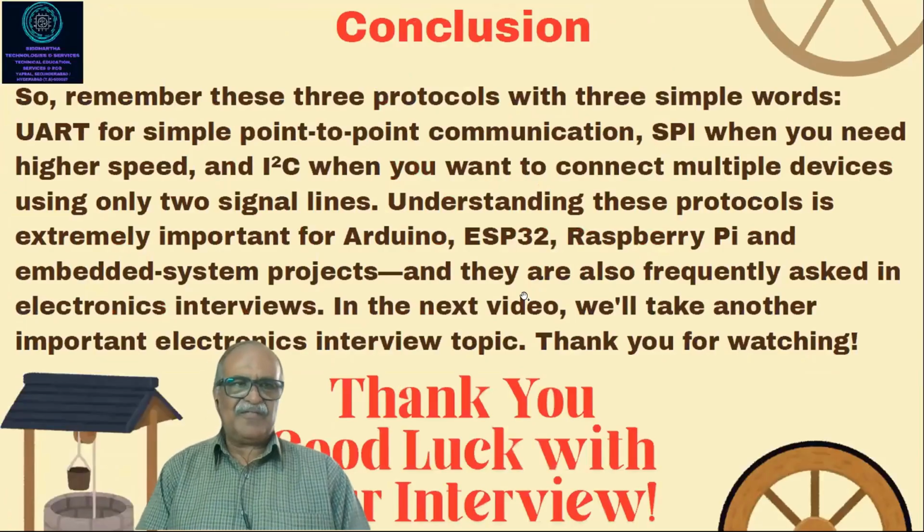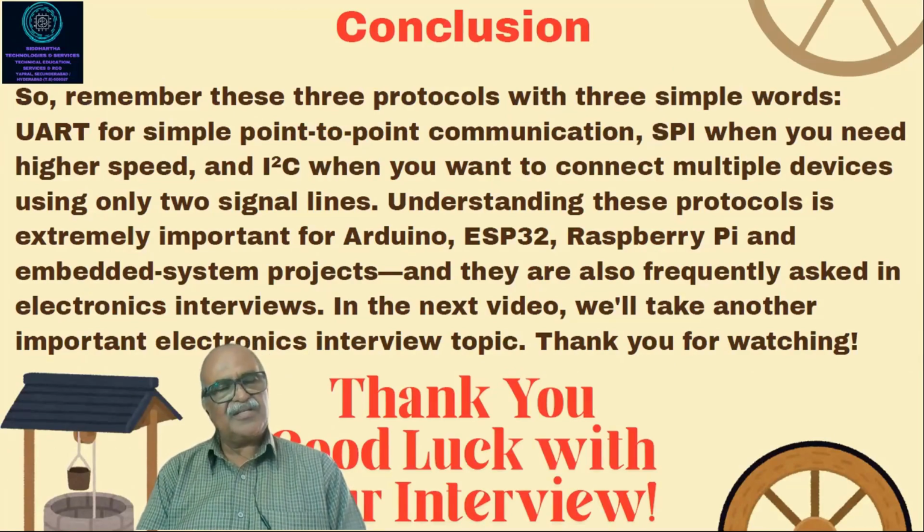So the conclusion: remember these 3 protocols with 3 simple phrases. UART for simple point-to-point communication. SPI when you need higher speed. Please remember, SPI when you need higher speed, and I²C when you want to connect multiple devices using only 2 signal lines. Understanding these protocols is extremely important for Arduino, as we have already discussed, Raspberry Pi, and different types of embedded system projects. They are also frequently asked in electronics interviews.